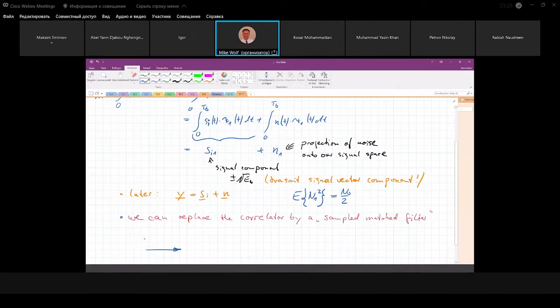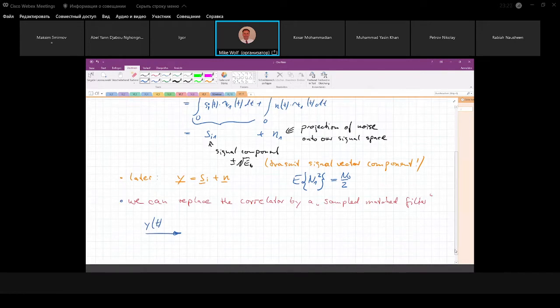So we still have this received signal, an analog signal. Our channel is analog. So we know this is the transmit signal plus the noise. And then we build a filter, and the impulse response g(t) of this filter is equal to c1(Tb minus t), because our integration interval is Tb. This is the important thing: c1 of minus t, and this Tb just makes a shift.